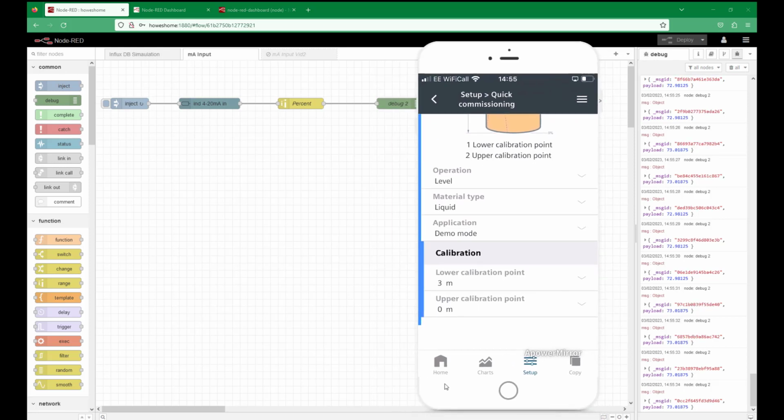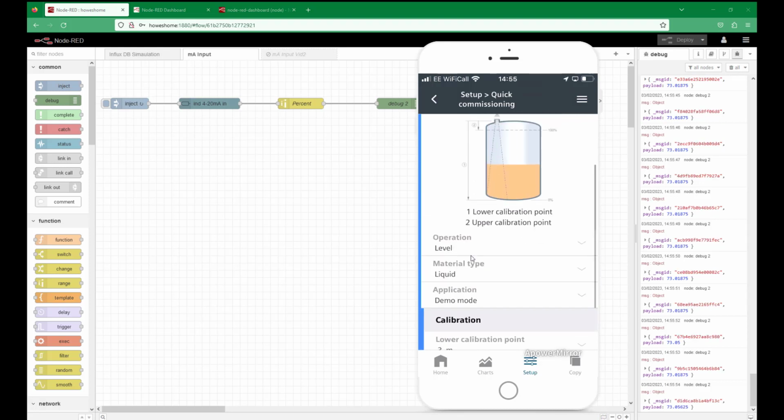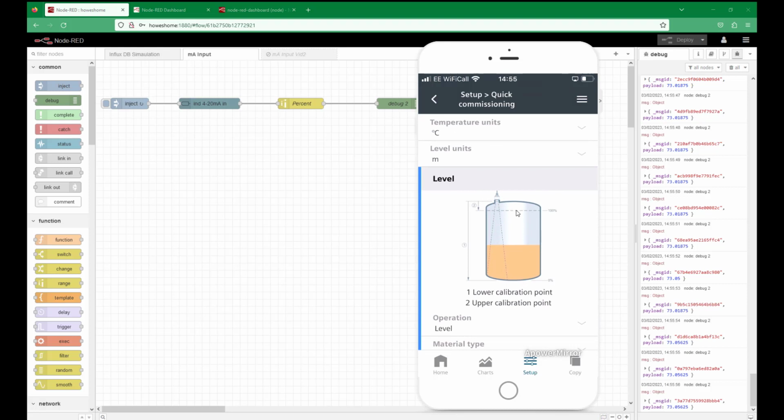This is a little bit difficult to understand when you're new to this, but because you're measuring level, when the vessel is empty, the radar will be reading 0 because the vessel is at 0%, and that will be 4 milliamps. When the vessel is full, it will go to its full level, which is 3 meters, which is 100%, which is 20 milliamps. We need this 0 to 3 meter scaling to be programmed into our Node-RED program.